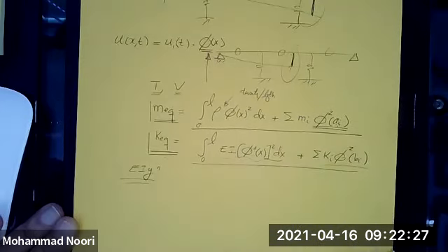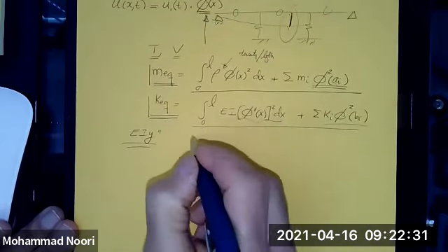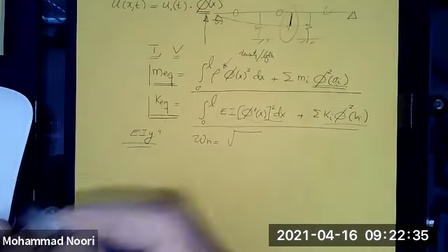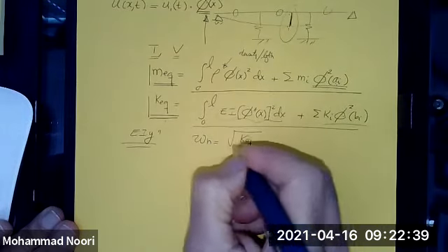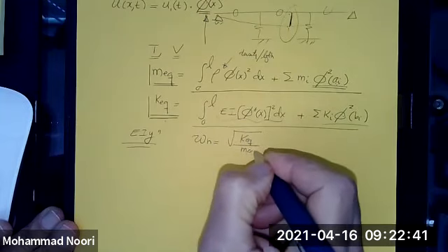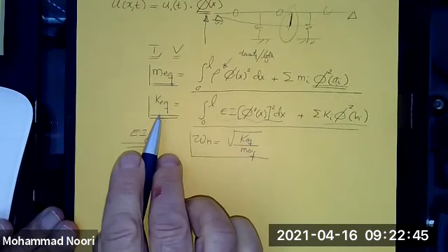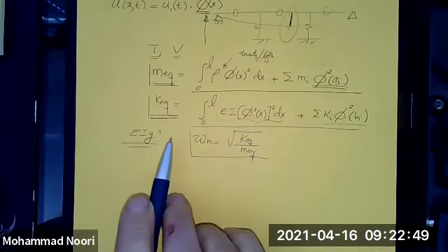So in order to find the natural frequency of any structure, you don't have to use the energy method from scratch. All you do is formulate the equivalent mass and the equivalent spring by using these Rayleigh's expressions, okay?